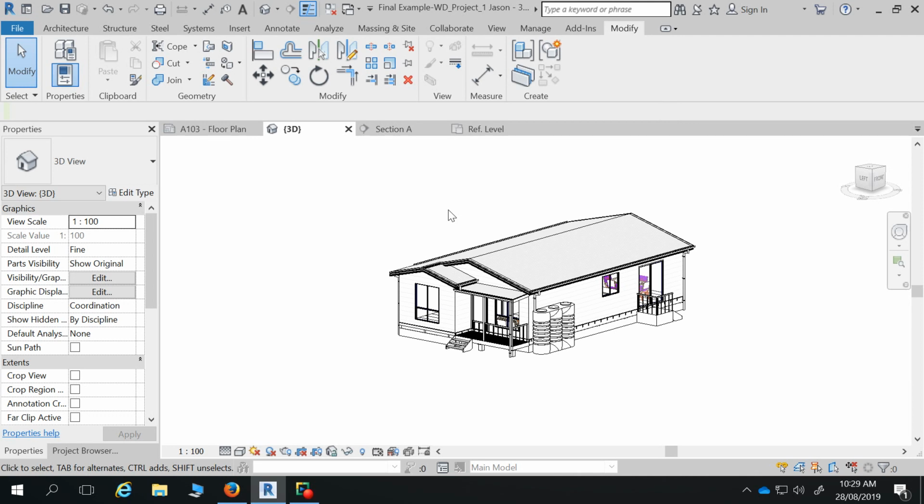So what I would do with that roof is edit that roof and make it just 90. So we want to replicate what the truss top chord is, the thickness of the top chord. And a top chord is usually, probably for this project, only a 70 by 35. But if you allow 90, it's fine. Sometimes they do use 90 on bigger jobs.